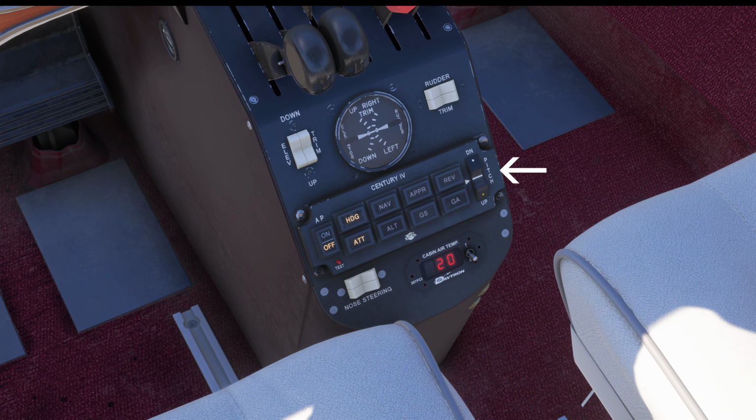On the right, there is a pitch wheel for selection of desired pitch in attitude hold mode. The wheel can be rotated by the pilot, but it also has a little electric motor inside, and it will sync to current aircraft pitch when the autopilot is powered on or when the attitude button is pressed.